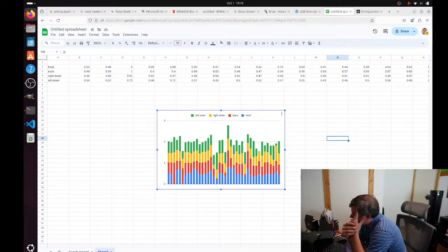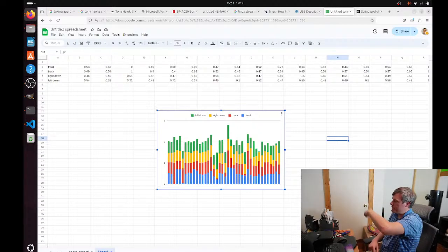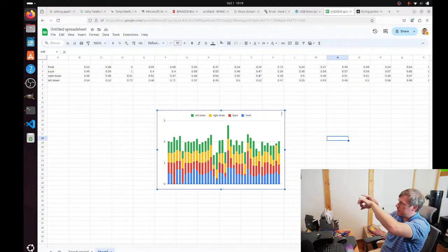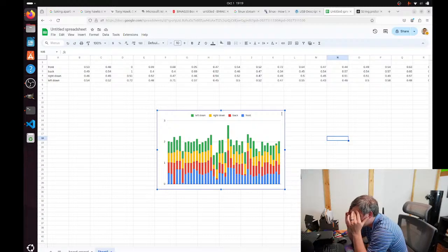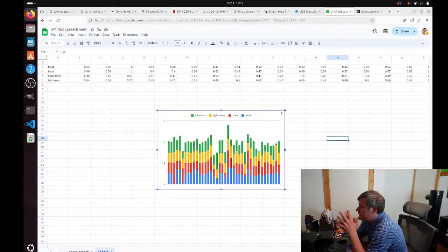In fact, I think that's actually common with these sensors. There's a bias, and so it could be that it always points in some direction, and so I have to calibrate it so that it's 0, 0. Yeah, no, that's actually a really good point.